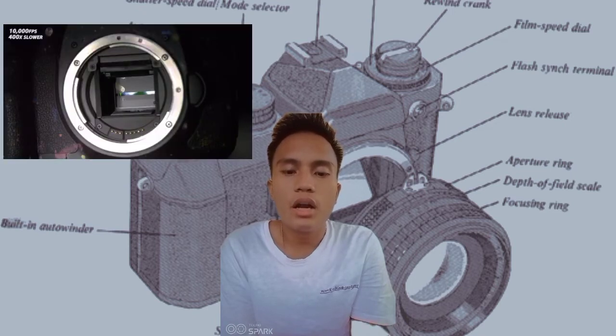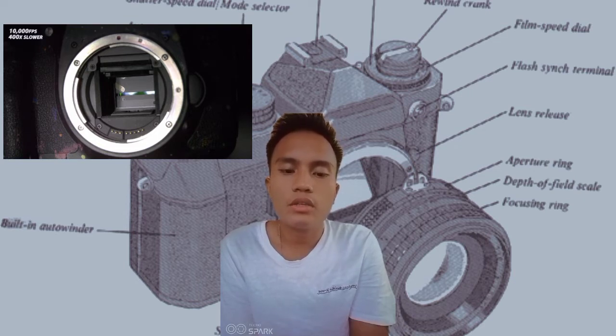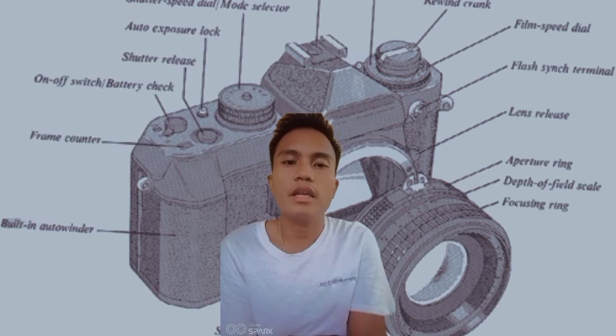Mechanical shutters are of two main types: focal plane shutters and leaf shutters. If your film camera comes with a focal plane shutter, it's likely the rolling curtain type. There are two curtains on the rolling curtain type shutter mechanism. The job of the shutter curtains is to open to allow the light to hit the film and then close immediately when the exposure is done, and so they're located inside the camera, sitting behind the lens.